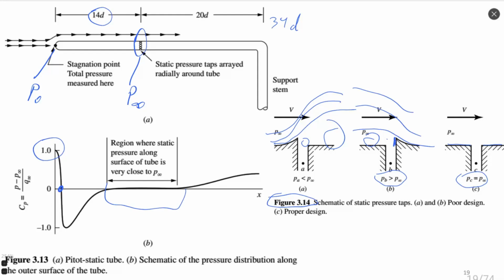This Pitot tube can be of different sizes. The smallest I saw was 0.5 millimeter or maximum 1 millimeter in diameter. And the biggest can be quite big, on the order of 1 centimeter in diameter. Small ones are usually installed on small scale wind tunnels where we need as little interference or disturbance of flow by this sensor as possible.